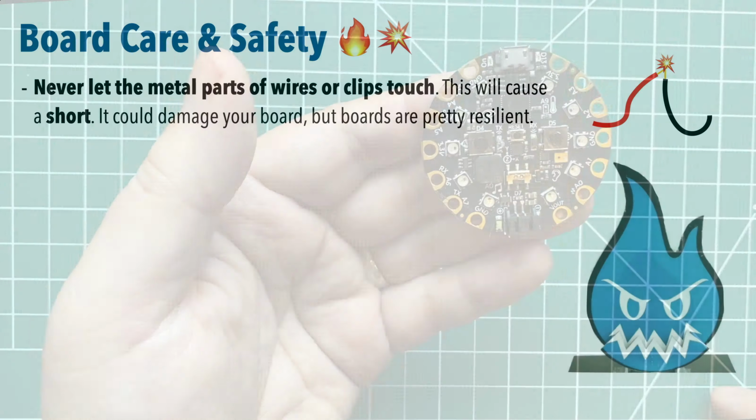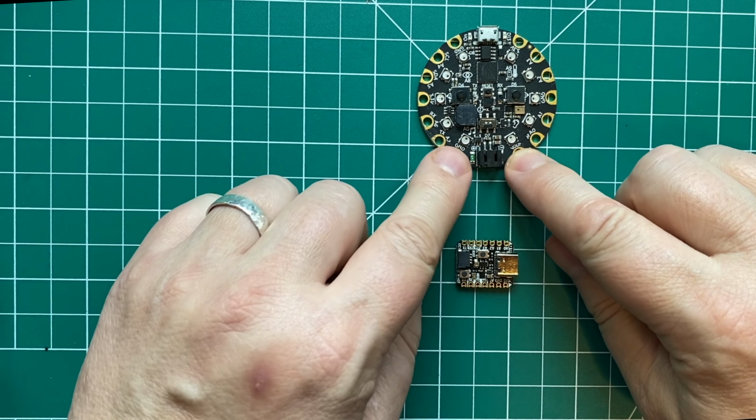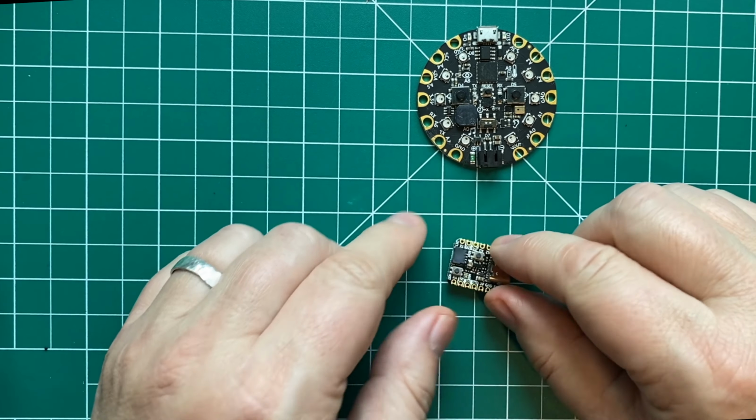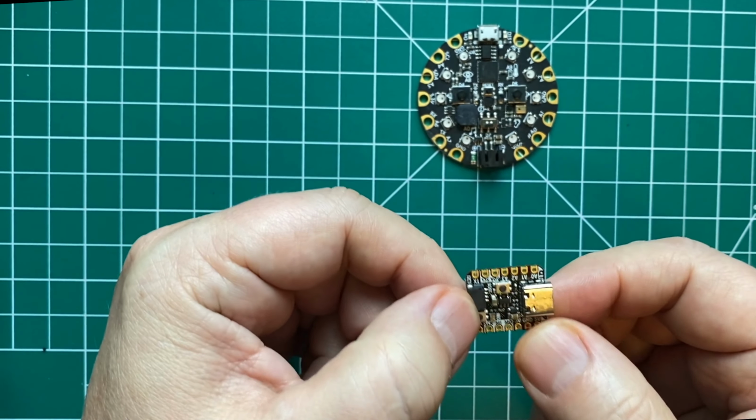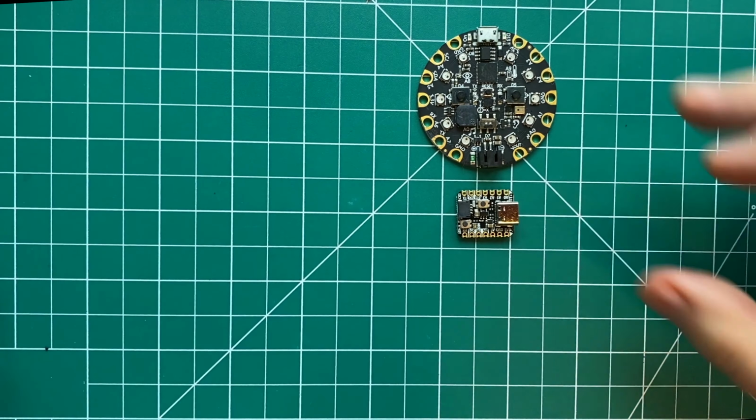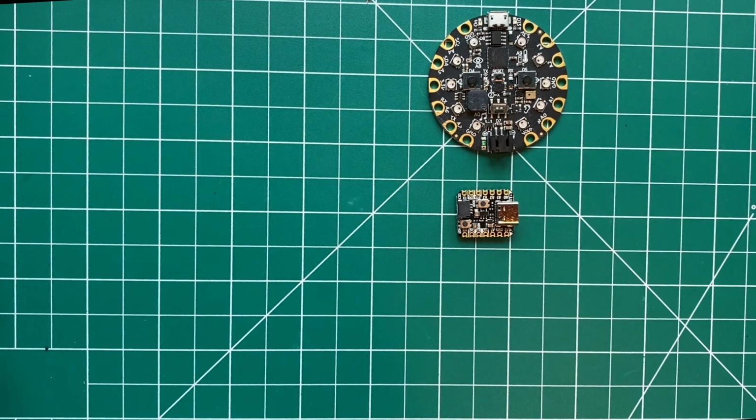It also makes sense to be careful when you're handling boards. There could be issues with static electricity, although again the boards are pretty resilient, but remember you also conduct electricity. So if your fingers touch multiple active pads on the board, especially if they touch power to ground, you might also create a short. So just handle boards carefully, and if things are plugged in and you're moving them around, try to make sure that you're not touching multiple pads at once.